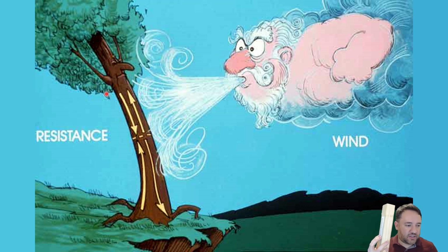So why is it that the tree has those strongest directions in the vertical? Well, that's because the primary structural load on trees comes typically from wind. And so wind is a lateral load on the tree, which wants to blow it over. In order to resist bending, you know from mechanics that we need to have tension and compressive stresses in the wood, tension on one side and compression on the other. So if I'm pushing this way, then I'm going to have tension on the near face and compression on the far face, just like is shown over here.